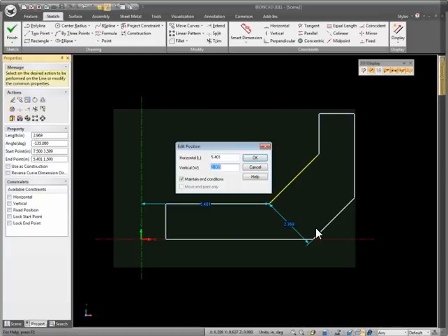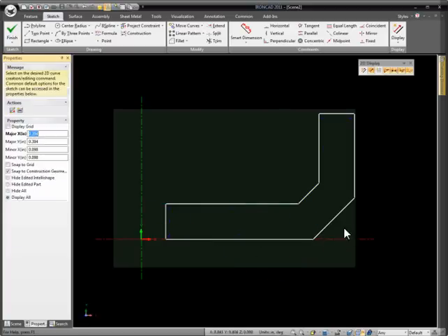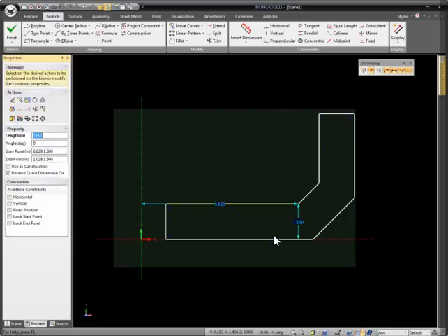So now we can just adjust that distance to be 1.5, since we want this end of the element to move, not the one that we already set. And now we have our constant thickness of 1.5 throughout the geometries. Now it's a key thing to note, if you don't change this back, it'll always maintain that. So when you pick on other lines, notice they're trying to maintain this weird angle association between our y, and now this is our x, if you will. So it's always nice when you're done with that to set it back to the x, y, z, so when you pick on other curves, you get back to a reasonable adjustment point.